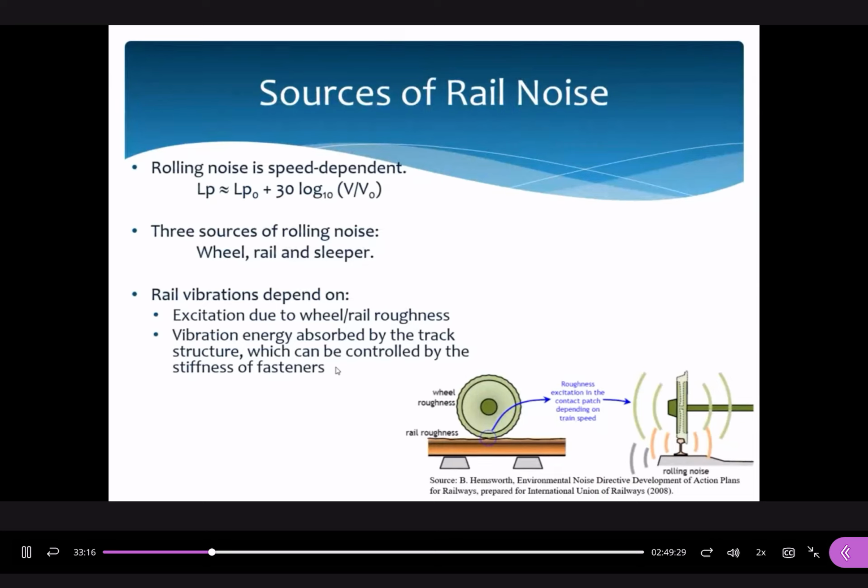How about the non-ballast type? You can reduce heights. What does it mean? When you go back to this one, this is a typical section to show the ballast type. When we design a non-ballast type, we can remove this part, because we don't have ballast materials here. So that's why the overall height of the whole track form structure can be reduced. So the first point is to reduce the overall height of the track form.